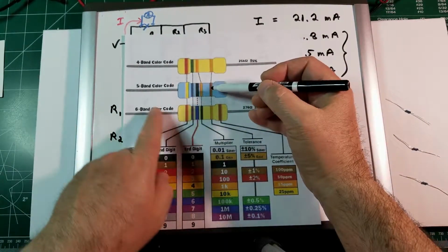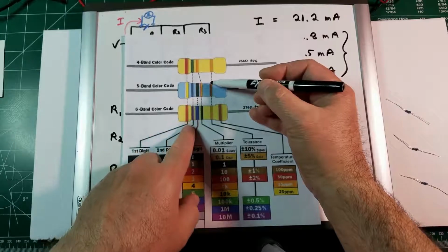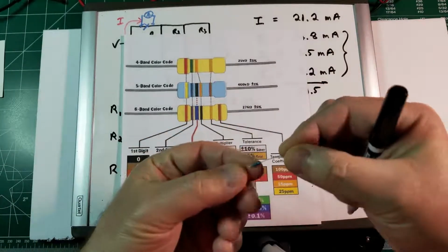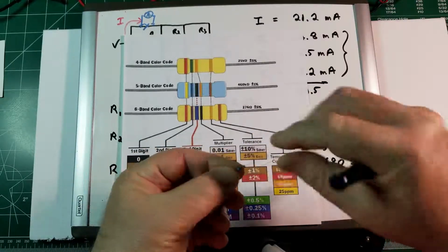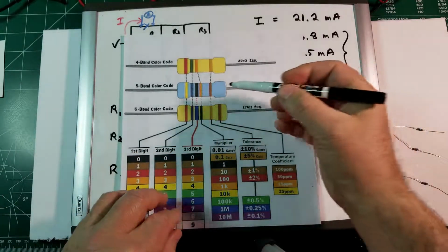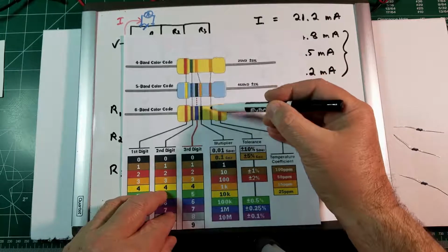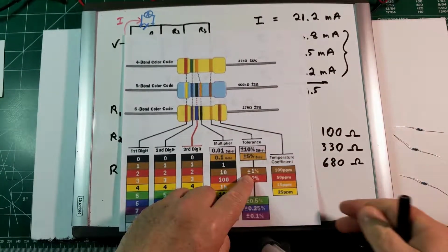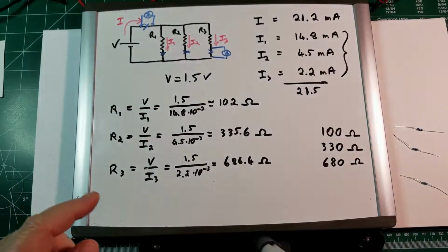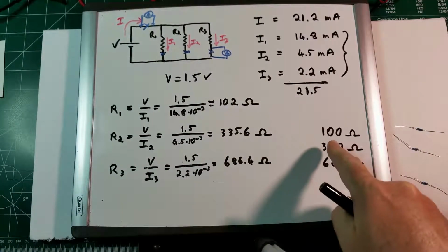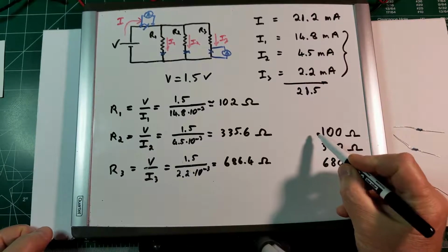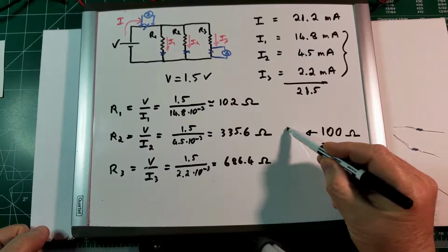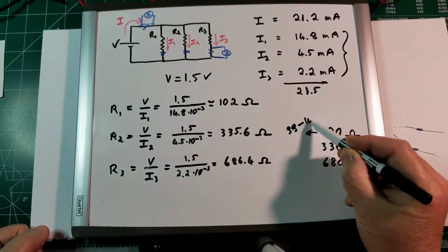In the case of our resistors, which have a 5-band color code, it is the last one. And if we take a look at each resistor, it's always brown, because that's the kind of resistors I had. And brown in the tolerance means plus or minus 1%. Which means that for this one, for example, the value 100, that is the nominal value of the resistor, can really be anywhere between 99 ohms and 101 ohms.